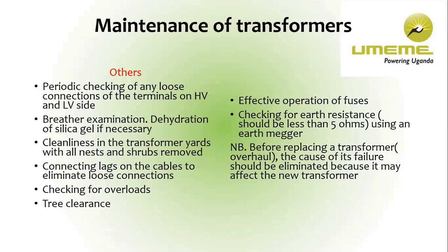And before replacing any transformer or overhauling it, you have to make sure that the cause of the failure is identified or eliminated, because it may affect the new transformer.